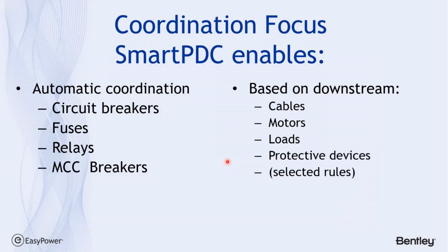SmartPDC, which is often referred to as automatic coordination, allows the user to automatically coordinate breakers, fuses, relays, and multi-case circuit breakers based upon the loading downstream, which includes cable considerations, motors, linear loads, and other protective devices based upon rules that you've selected in the setup of the features.